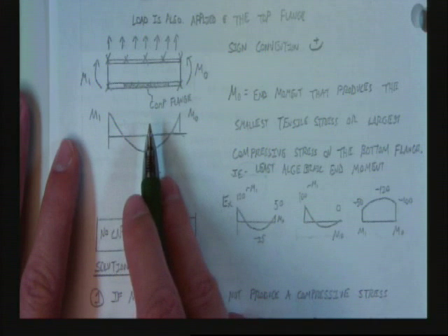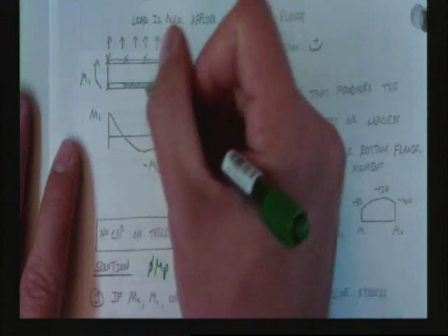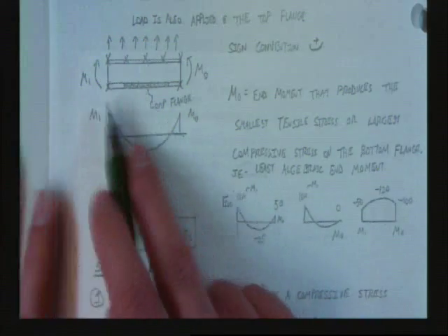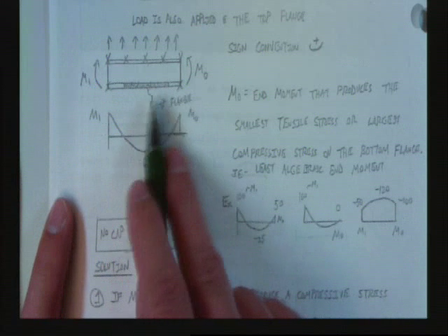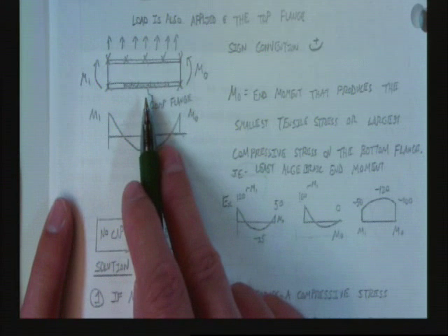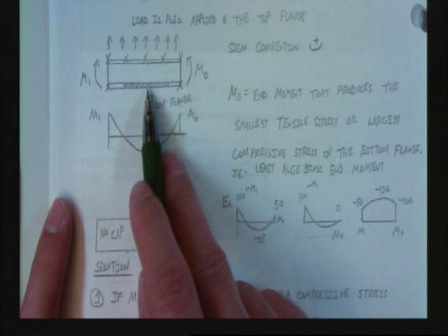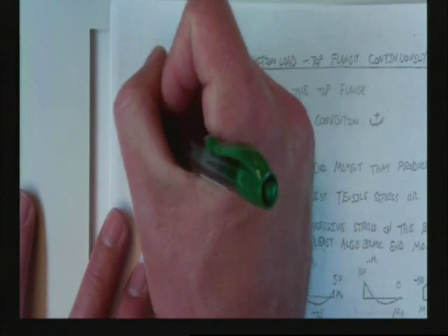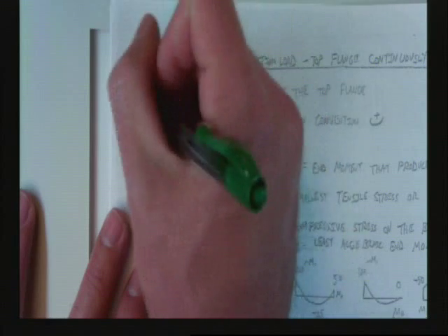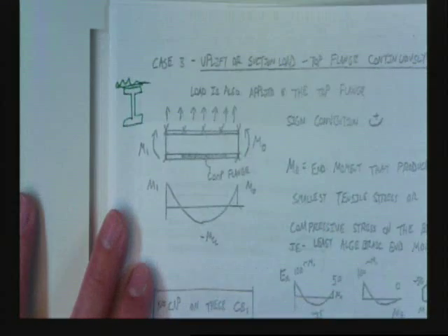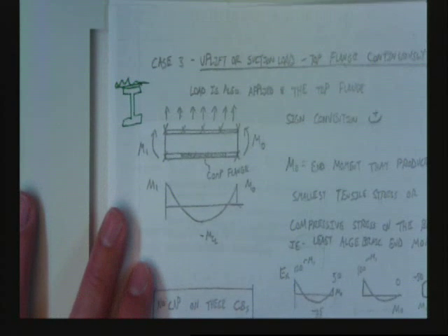That makes sense? And if you have a brace top and bottom here, it doesn't matter whether the wind's going up or whether the wind's going down. You've got a brace here, here, and here. You're good. It's only in these circumstances when you say, oh, I don't need to brace that. And you might not even think about it because really we have a beam here. This beam's got some kind of roof material on top that we're trying to rely on to be a brace.